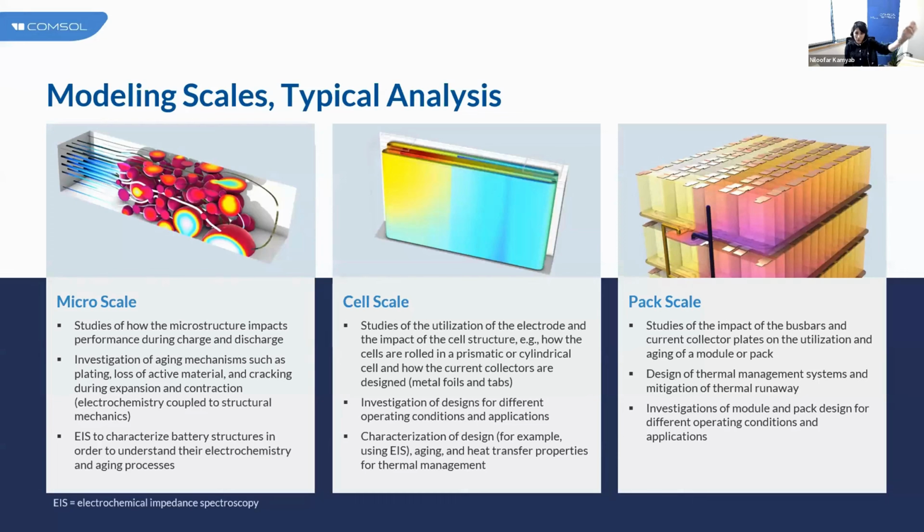Lithium ions shuttle from the negative side, go to the cathode, sit inside the porous electrode, and then you flip the sign, and they exit the porous electrode and go to the other side. That's just shuttling back and forth of lithium ions between two electrodes. You get to resolve exactly what is taking place, how it's taking place, and exactly how the structural details of the porous electrode impact that.